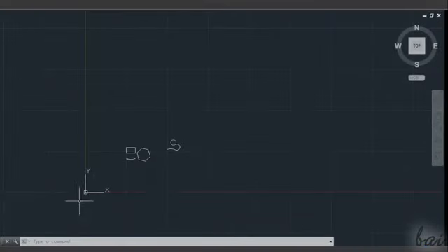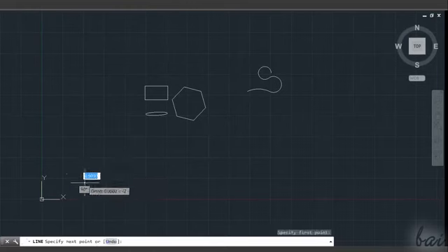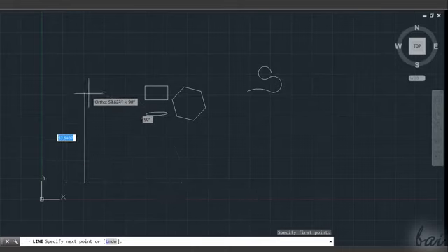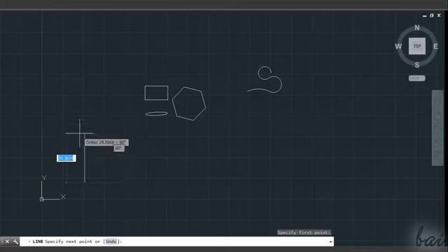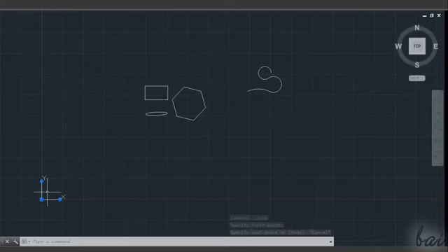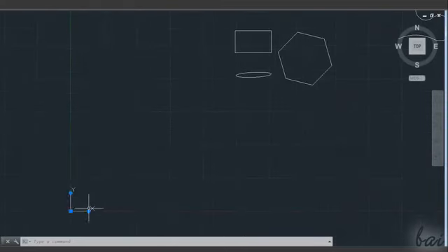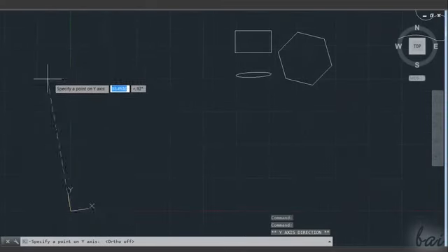Very important is also the gizmo, the Cartesian system placed on your AutoCAD project. This is a reference used to locate the two main directions of a 2D project, the x-axis that represents the horizontal direction and the y-axis indicating the vertical direction. You can click on the square node to move its origin and use the rounded nodes to rotate the reference system.